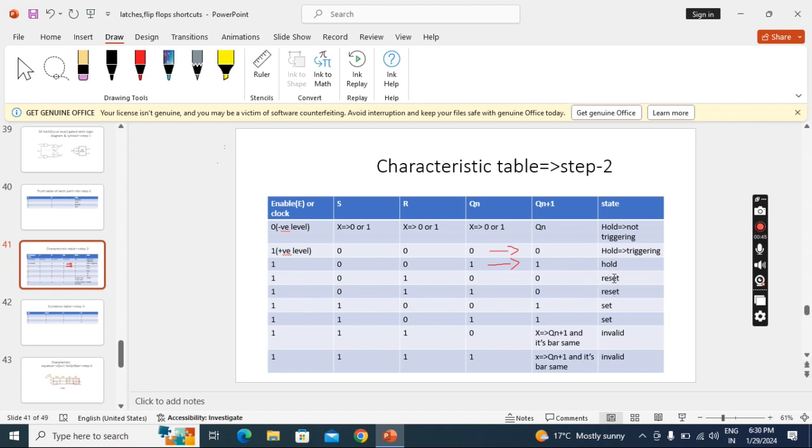Here reset is coming. So reset means value 0, 0, in both cases 0, 0. Observe once, this 0, 1 is going to the gated part, not to the latch part. But the latch part is getting 1, 0. That's why reset. That you have to observe. Next condition. Similarly, the driving part gets 1, 0, but the latch part will get 0, 1. When we get 0, 1, we know it will become set.